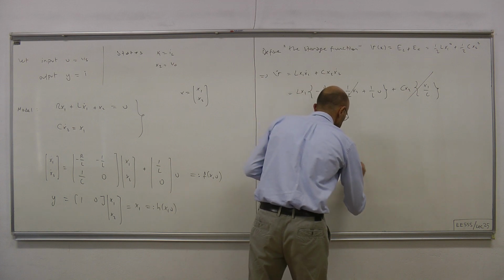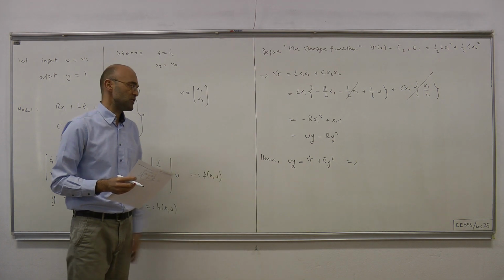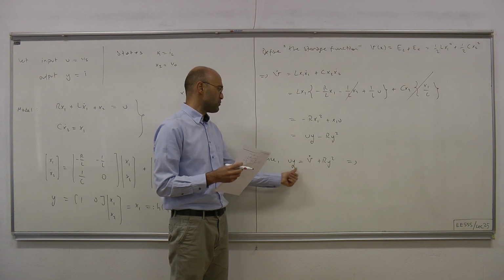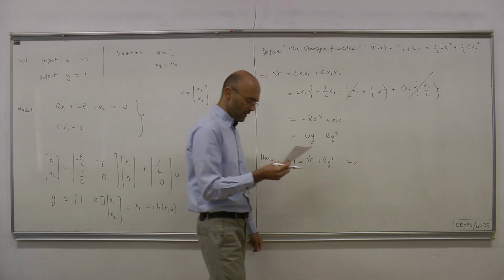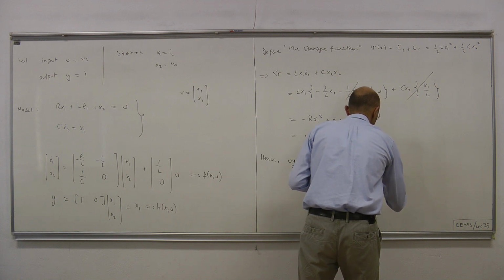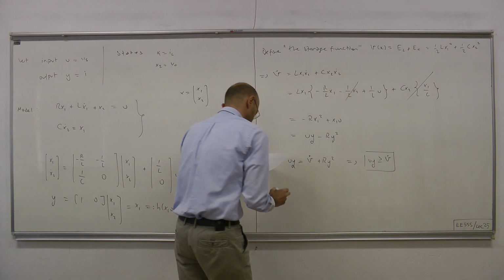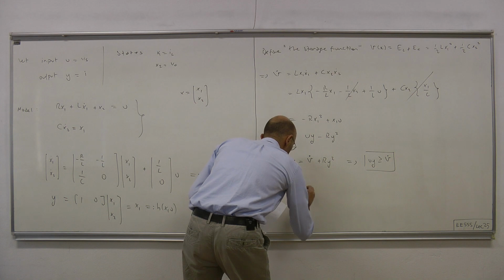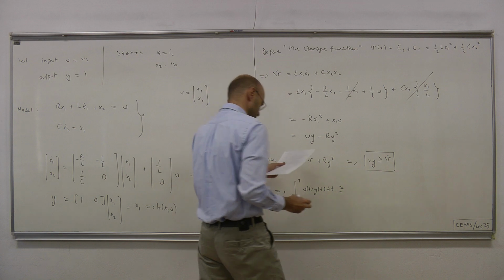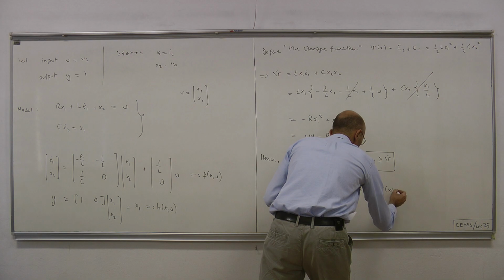Okay. Now, since we're talking about passive components, by which we mean positive R, L, and C, this thing is never negative. Hence, u times y is never smaller than V dot. Okay, u y is always greater than or equal to V dot. Okay. So that implies this integral of u(t) y(t) dt is never less than this difference, V of x(t) minus V of x of 0.